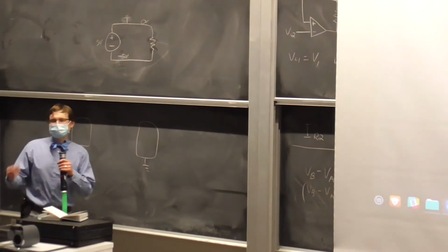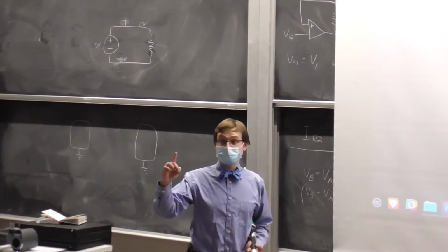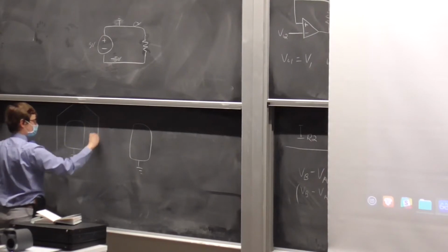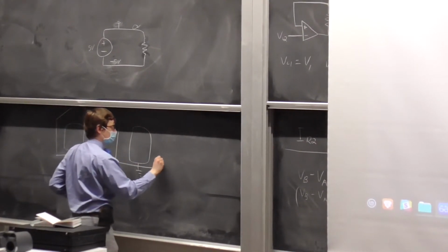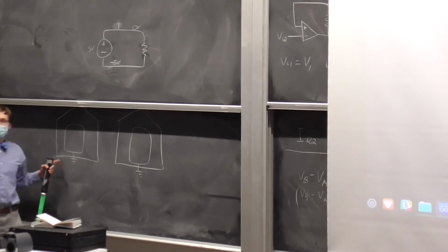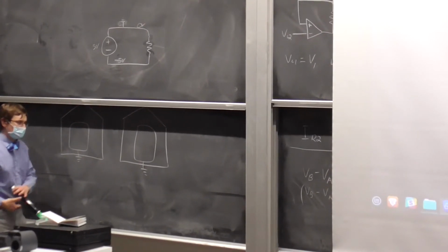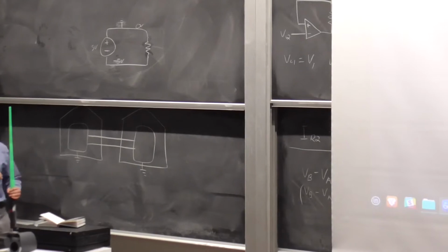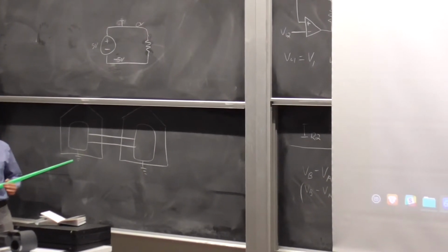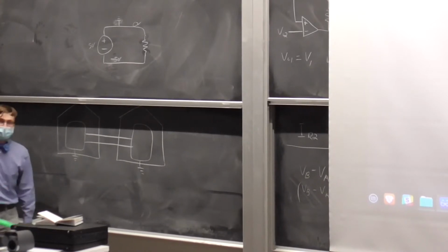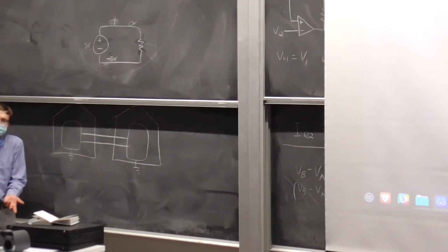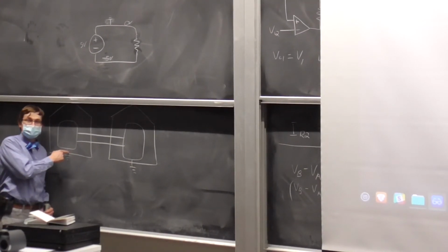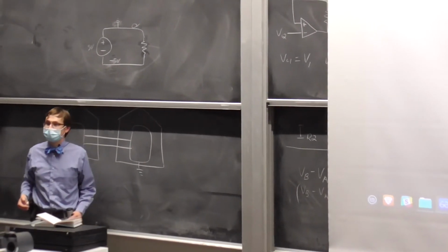Let's imagine these two devices are inside different houses, with two different grounding plates, communicating with each other. What happens if these ground plates have a potential across them, due to soil acidity or something? What one person thinks is ground is not ground to the other.